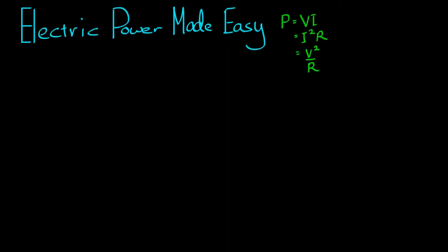that. The number one thing I want to emphasize when you're using these formulas is you use what you have. So if you have the voltage and the resistance over a component, unless you're specifically asked to, don't go and find the current so you can use this formula up here. Just use this one down here. And you can often find the power dissipating in certain components without necessarily knowing the resistance, the current, and the voltage. You only really need 2 out of 3.